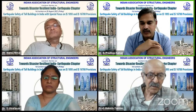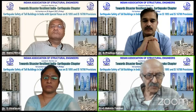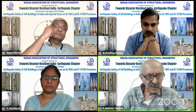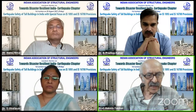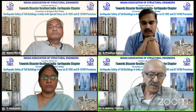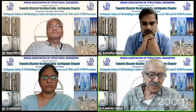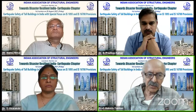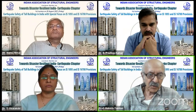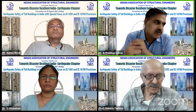and then we can propose or we can improve our code empirical expression. I think before we end, there are a couple of questions by Mr. Amit Patil, which I think need to be addressed. As per amendment number 2 of IS 1893, the first 3 modes, 65% participation provision is not applicable to buildings with large podium in lower storey. Can you elaborate it? Yes, sir.